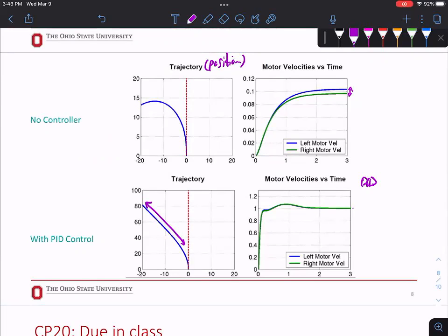It would actually be more advanced, but a system could have multiple interlocking controllers. So if you wanted to control heading and velocity, you have to create a cascaded controller, which would have its own Ki, Kp, and Kd. So there will be 2 sets of PID values. They could all be PID type controllers, all right?